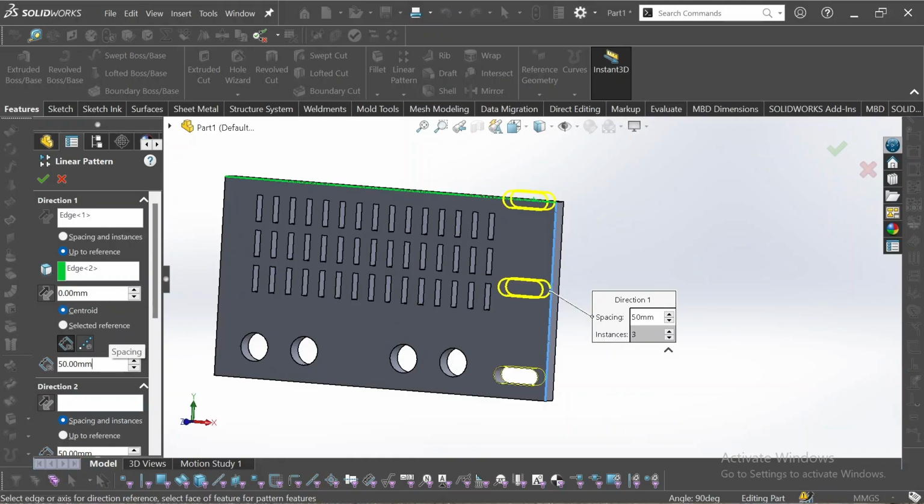Okay, it's going to, how will I put it, linear pattern the cuts to any amount it automatically picks out due to the value you give it here. It's going to stop at this edge. It's not going to extend past this edge. So let's say we make it 10.